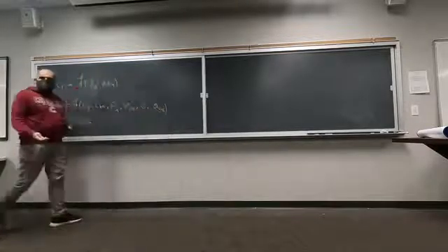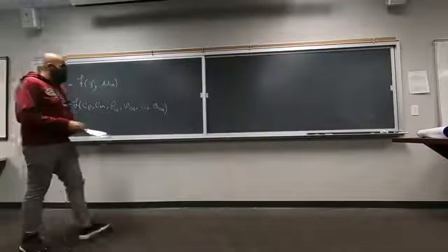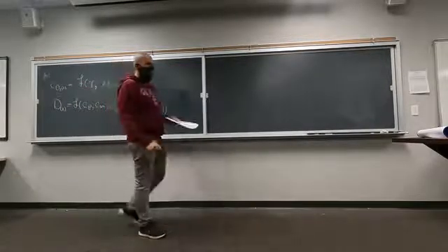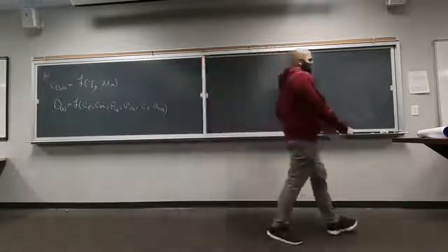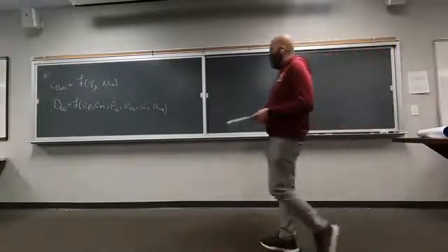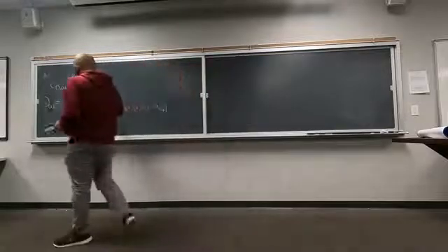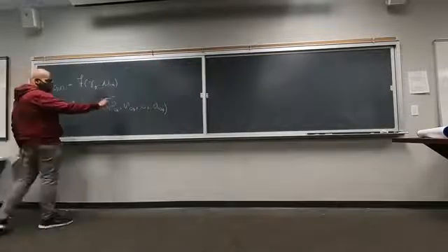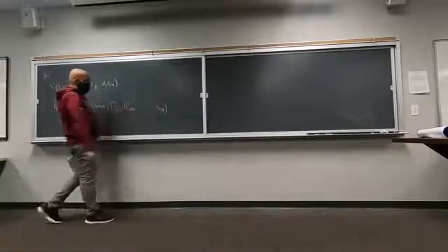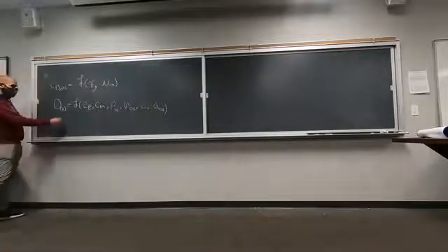So in supersonic flight, Mach number becomes very important, right? So we need to include a free stream Mach number because it becomes important. Mach number itself is a function of temperature, if you recall. Okay, so these are the independent variables: Cp, Cv, rho infinity, V infinity, C, where C is the chord length, and a infinity. And we also have 1 dependent variable.